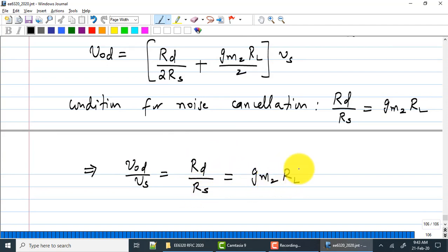When you take the differential output, both sides have the same gain for signal, I mean, opposite phase for the signal, so that when you take the difference, signal is additive. So as you can see in the noise cancelling LNA, the magnitude of the gain through the two paths is the same for the signal portion with opposite signs.